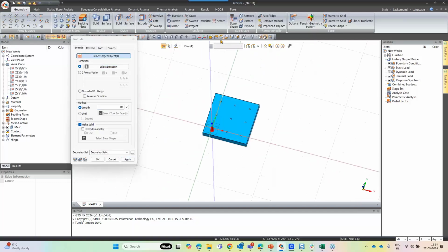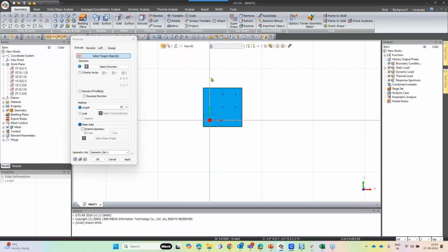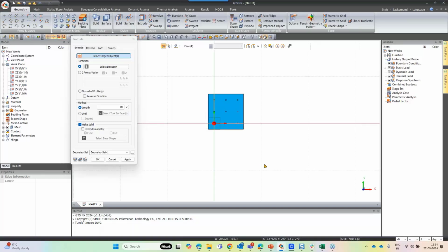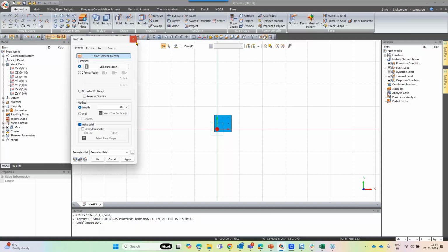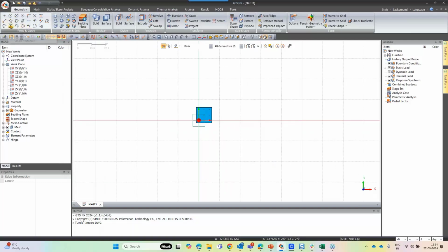And now the next step is to model the soil. So the foundation modeling has been done. In this particular scenario which I'm showing, I'm just creating the raft, which is the only foundation that we have, and there are no piles in this scenario. So the next step is to create the soil continuum body.